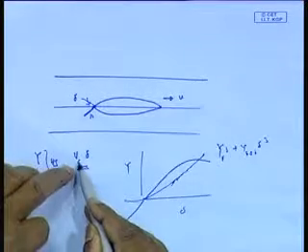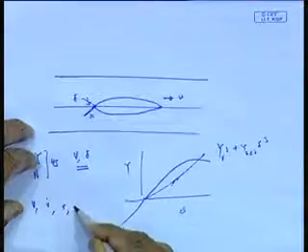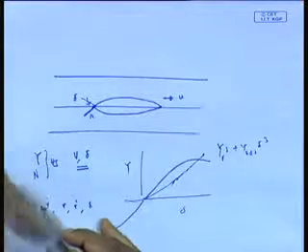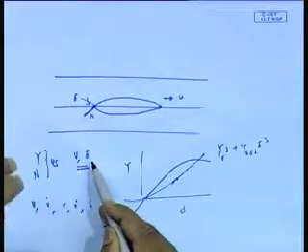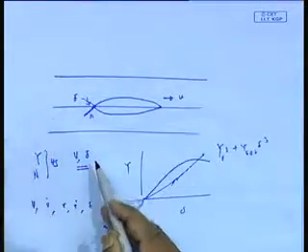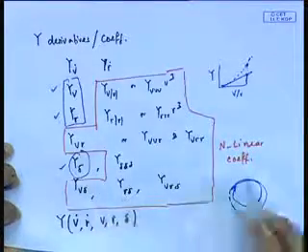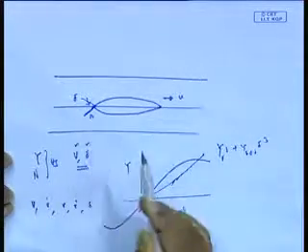Let me call the other one sway velocity derivatives. This is sway velocity V, V dot, r, r dot and delta. Sway velocity derivatives I can find out, linear and non-linear. That linearity does not come in the picture here. I can find out rudder derivatives. Now, after this break, I will tell you how I can also find out Yvδ, or if you want Yvvδ, Yvδδ, the cross coupled terms. It is possible because I have varied these two, so I can always vary these two independently. I will tell that later on.